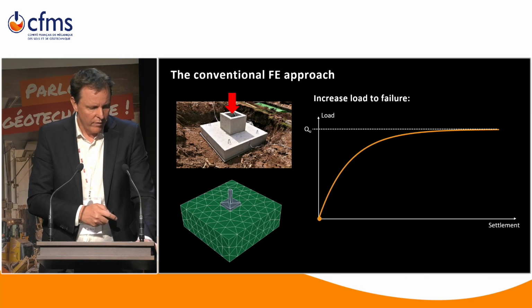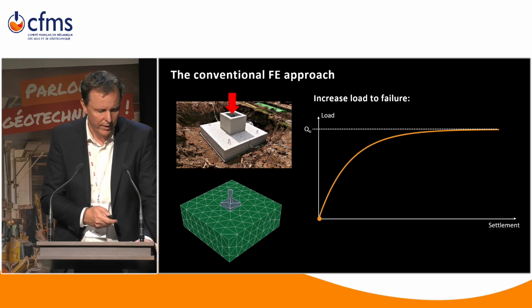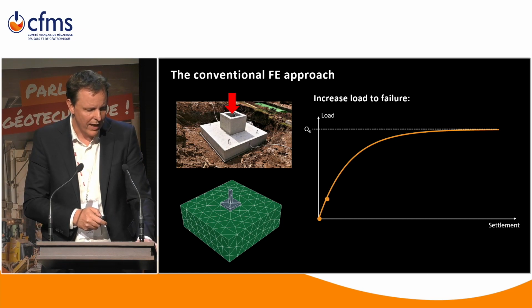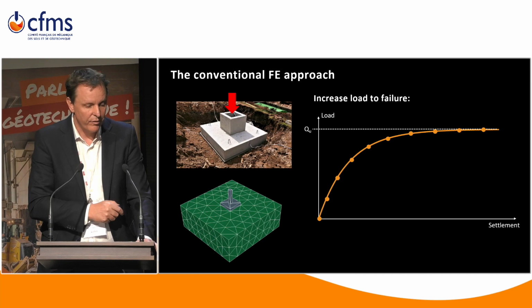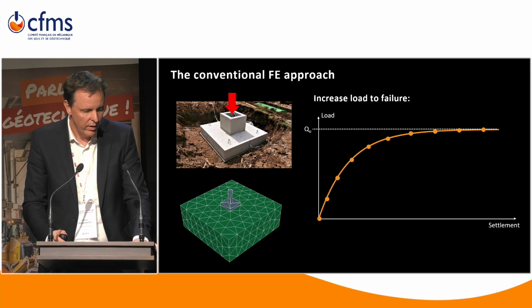With the conventional FE approach, solving that problem involves a more or less fictitious simulation, which is not really necessarily what you want to be doing, but it's what you need to do to solve this question that you're asking, what is the maximum load? So you set up a finite element mesh, and then you start increasing the load, you start stepping up, and at some stage you will have large displacements, and you identify that with failure, and you read off the maximum load.